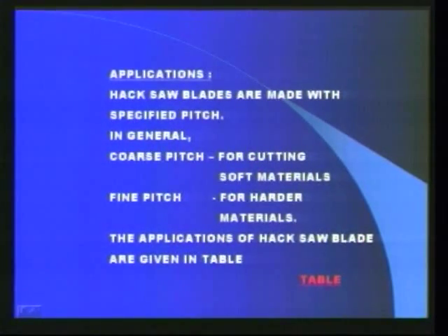In general, the blade with coarse pitch is adopted for cutting soft material, while the blade with fine pitch is used for harder materials. When cutting thin sections, at least 2 teeth, preferably 3 teeth, should always be in contact with the workpiece. Therefore, blades with fine pitches are recommended for thinner sections which are not suitable with coarse blades.